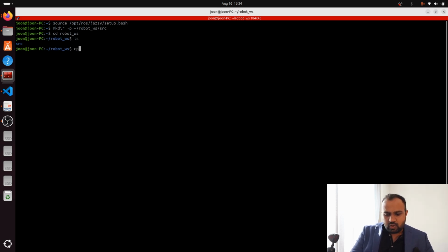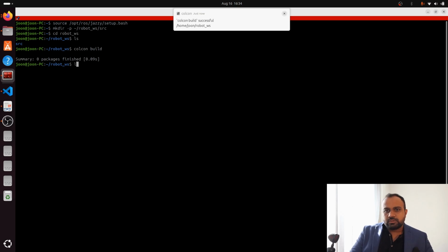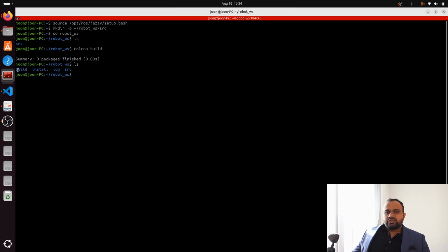Let's check. Okay, now we will do colcon build, and let's check. Now we have extra folders: log, install, and build. These folders are not created by us, they are automatically created by the colcon build, and you will create your packages inside src. So cd src, you should create the package here. Now there is nothing inside it, so we're going to create our own package.